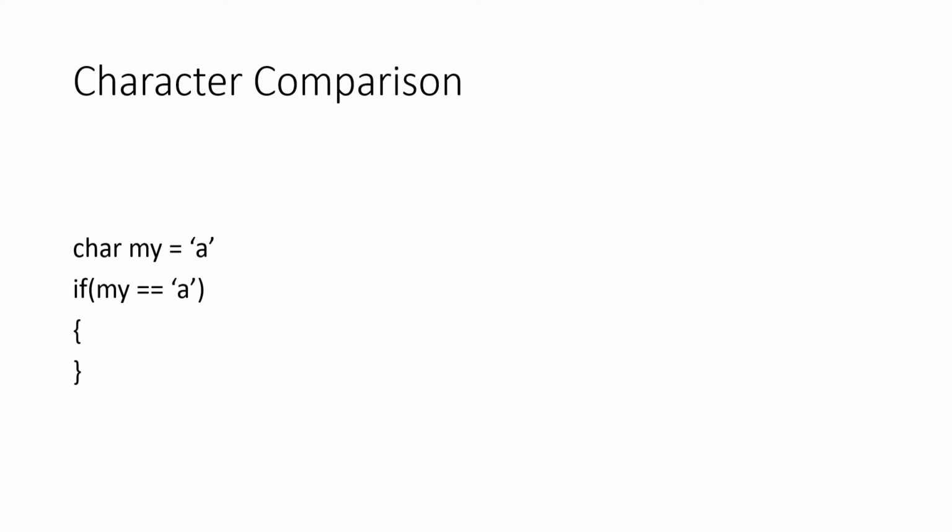Now, when it goes into the embedded domain, probably this input is coming from a computer or from a GSM modem or from Bluetooth or probably any number of things. So a microcontroller or a system can accept data serially and can print out the data serially, or your print function can be done on an LCD or a graphics display or an OLED display. In any such case, and in many cases, you will need to compare whatever you have received. Now, to compare strings or characters, there is a very simple way. First thing is, if you have to compare a single character with something, then this is how you do it.